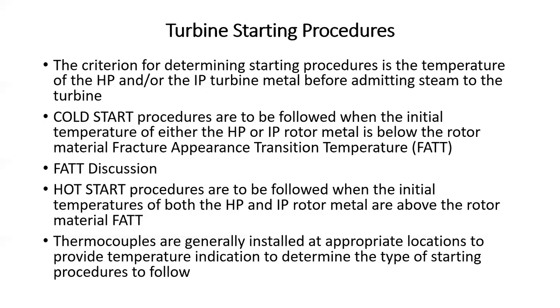Okay, hot start procedures are to be followed when the initial temperatures of both the HP and IP rotor metal are comfortably above the material FATT. So there's no doubt that the material will act in a ductile sense in terms of cracks, crack propagation, crack growth, resistance to thermal fatigue and other stresses. And I mentioned this, but thermocouples are typically installed at appropriate locations to provide the temperature indication to determine the type of starting procedures to follow.